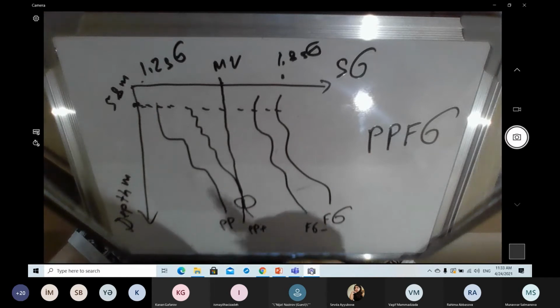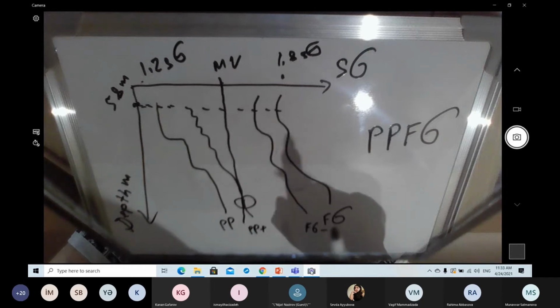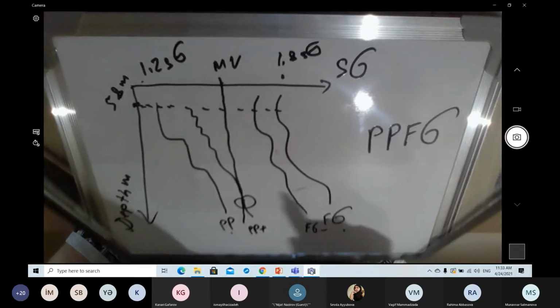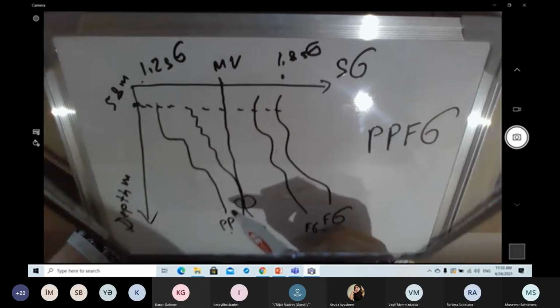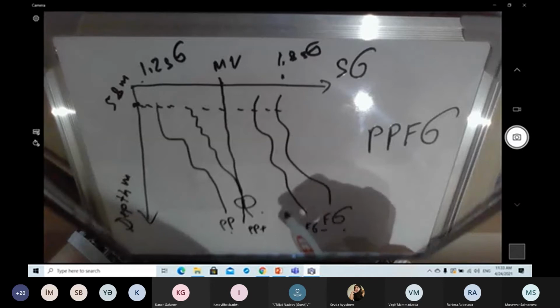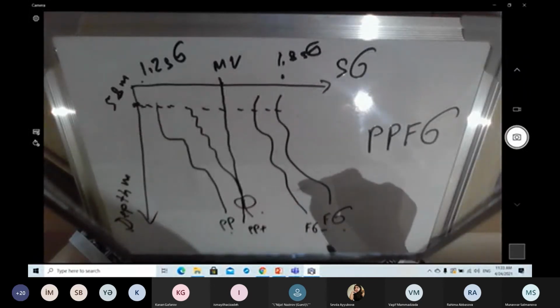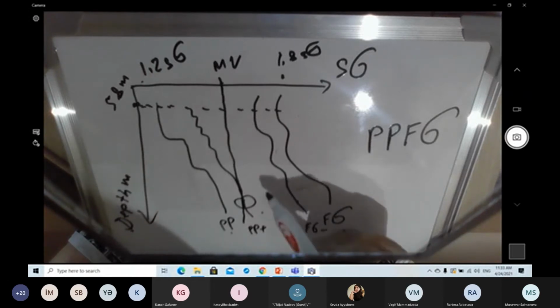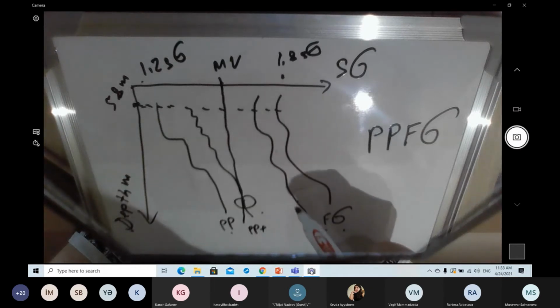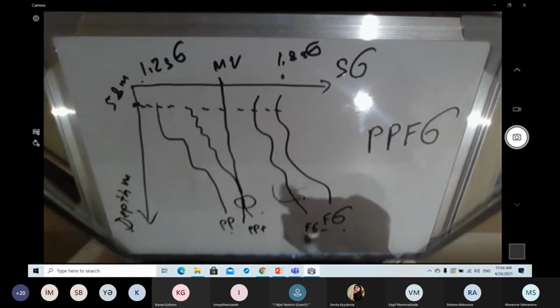It is a basic rule in drilling that during drilling, cementing, whatever phase in the drilling process, we should be between PP and the FG. We cannot go below PP because pore pressure gradient means that we will have an influx, a kick, into the wellbore. And if we go above the frag gradient, it means that we will have a lost circulation problem. So we will frag the formation, and our wellbore fluid, it doesn't matter whether it is mud or cement, if we are pumping slurry, it will go into the formation, and we don't want that, right?